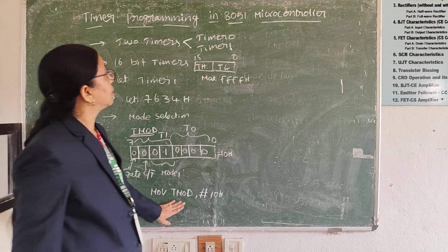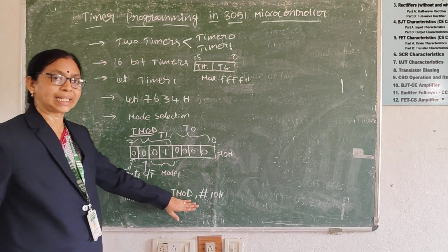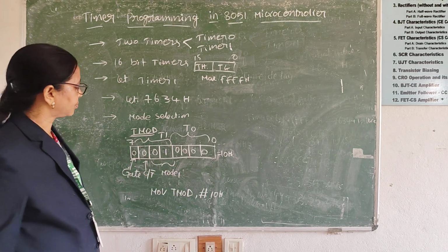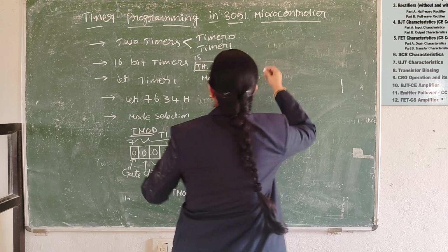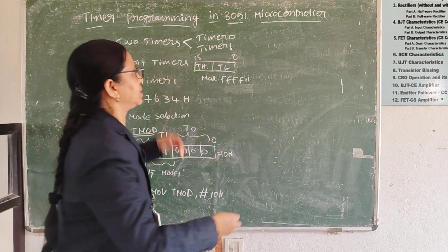This command instructs the 8051 to operate in timer 1 and in mode 1. Now we have to load the initial value in the timer registers.